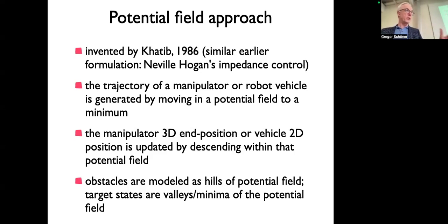The same approach can be used in these two ways. And the notion is that you are erecting a potential field. A potential field is just a scalar field, where for every location in, let's say, configuration space, or for the vehicle, it will really be in position space, the kinematic state of the vehicle, not velocity, but its position, which could include orientation.